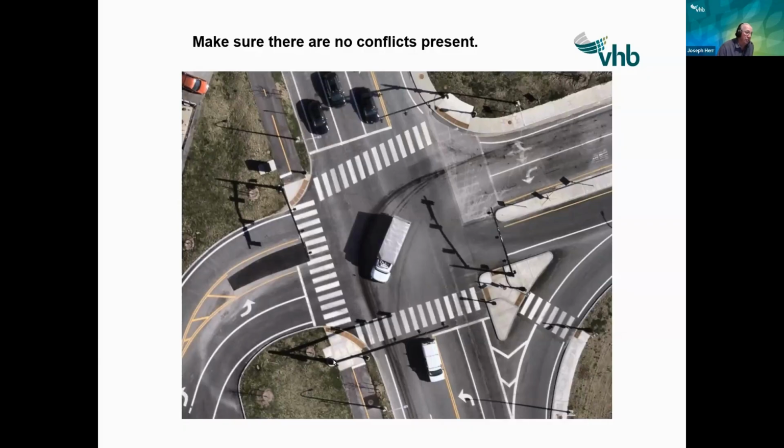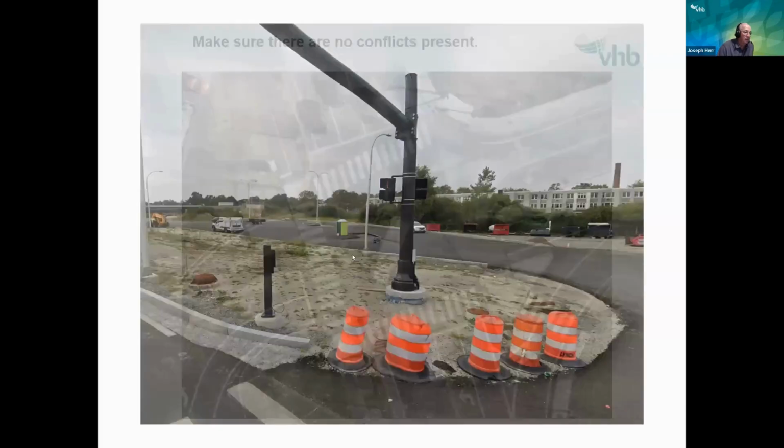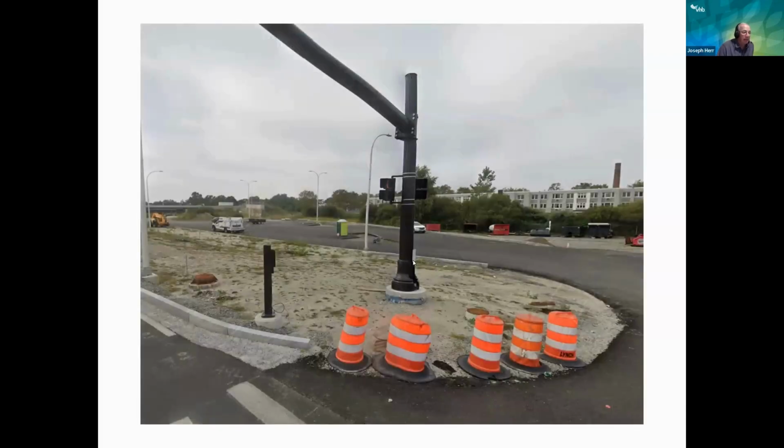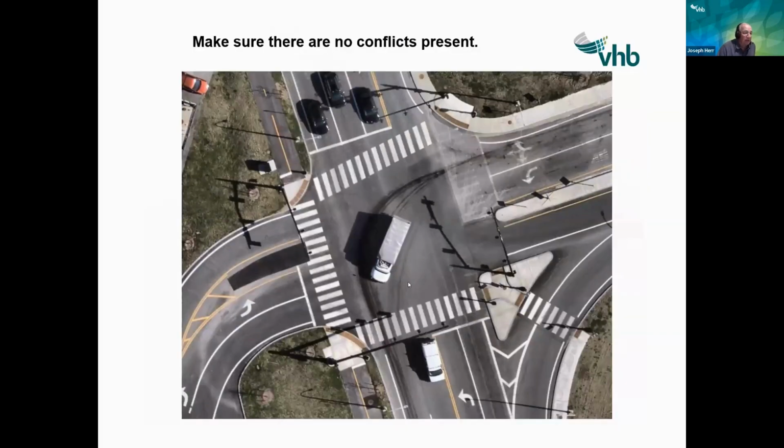It was a wiring issue when it was initially installed. So what happened, this button, which goes across here, was connected to the wrong PED head. And that was done out in the street. You had 2 PED buttons, 2 PED signals, and it just happened to have cross wiring on it. And fortunately, it was caught during the inspection.